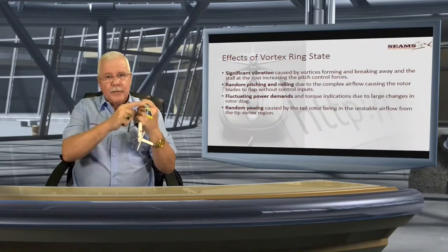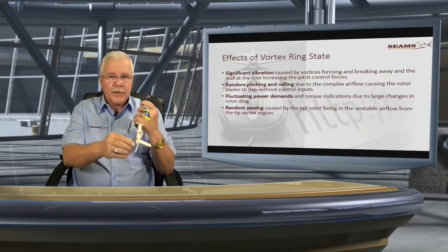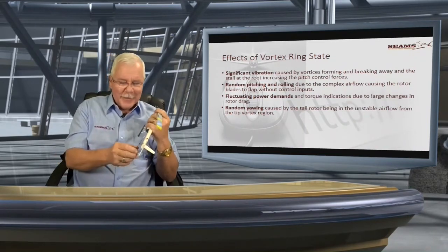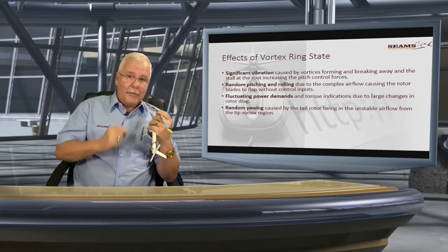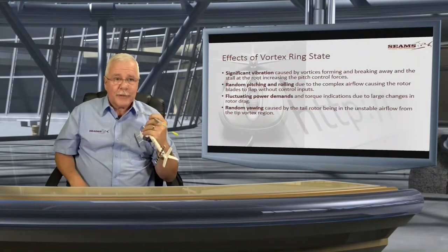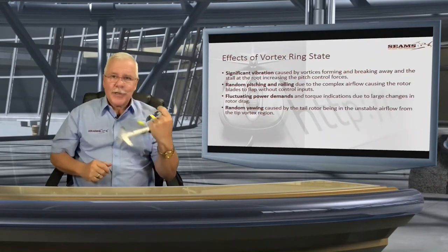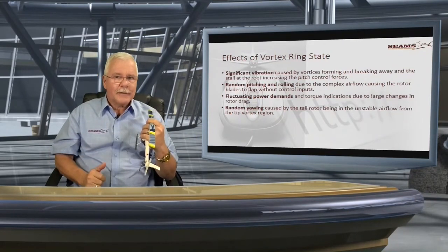But in stress conditions like this, when you're hard maneuvering and low, it can take up to 15% of your engine power away. You've already got not enough power. Why would you decrease the power available for the main rotor blades? Because that's your problem. We do stuff like that because we don't understand. So yawing is not the answer, because you're throwing away energy that you haven't got anyway.